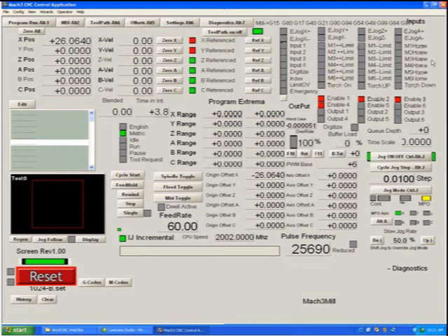Typically, you'll have none of these on when the signals are not active and the program's in a normal runtime state. Normally, the only thing you'll see flashing around when you're not moving is this time in interrupt DRO, which shows the number of microseconds that the driver is currently spending on each iteration through its interrupt cycle. I don't expect many of you to understand what I just said. Just take it from me that this number should be flashing, and it's quite normal. It should be less than 15 on all systems, and you can see mine flashes between about 6 microseconds and 4 microseconds, depending on how much housekeeping needs to be done at that particular interrupt.